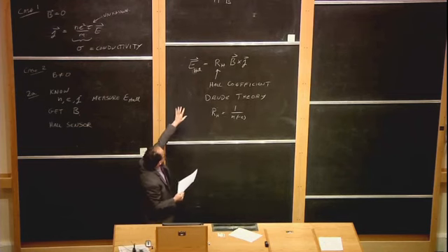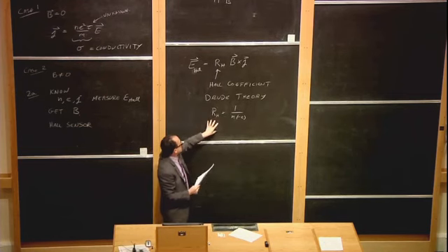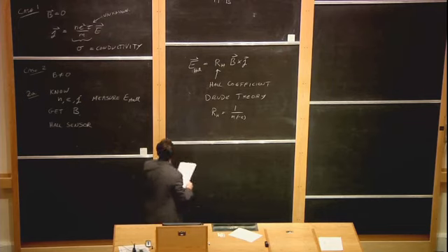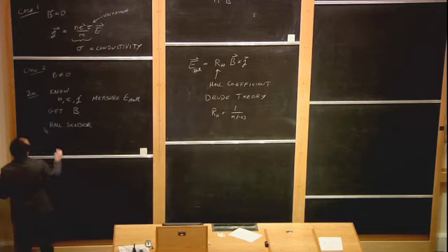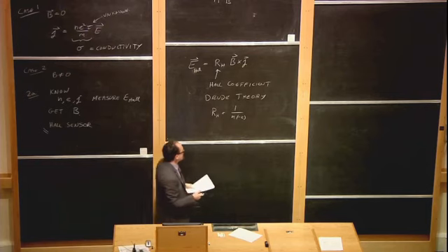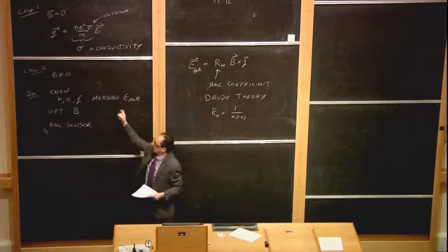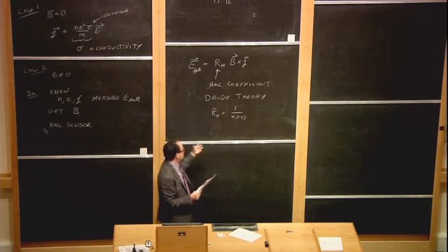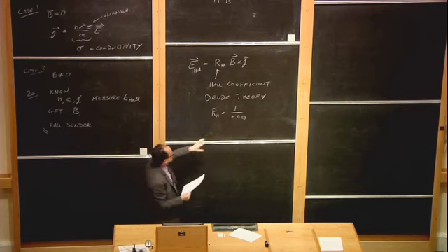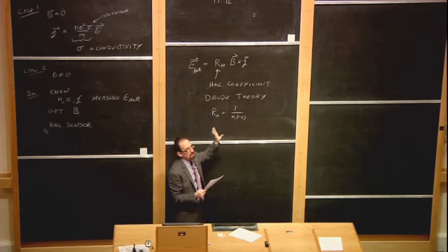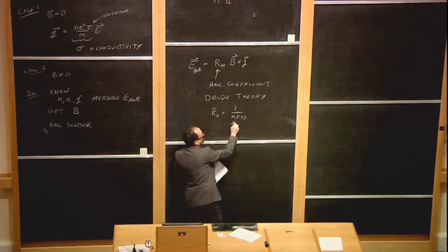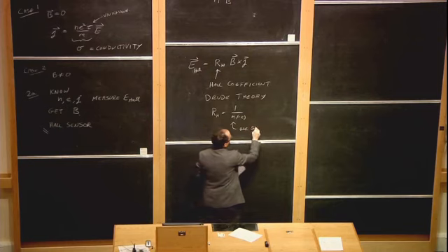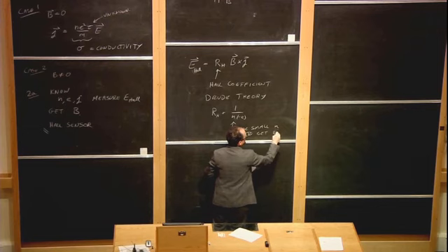So the Hall electric field that you would measure would be proportional to the Hall coefficient here. And if you're trying to build a Hall sensor in order to find accurate ways of measuring magnetic fields, using electronics or using voltage measurements, you really want the Hall voltage to be as large as possible, so that you have a large electric field to measure. So to do that, you usually choose a material with a small density. So use small density to get big E.